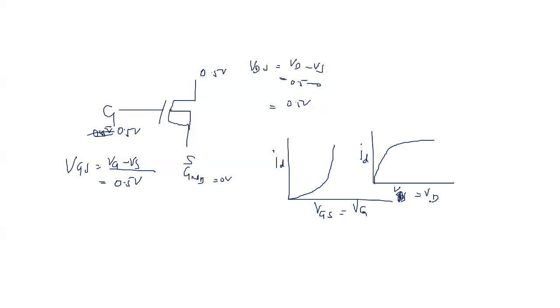on ground. Now what we have done is we have taken the ADL window, analog digital library, and in this ADL window, I have selected drain current as output. Then in my DC analysis, I can select my x-axis.